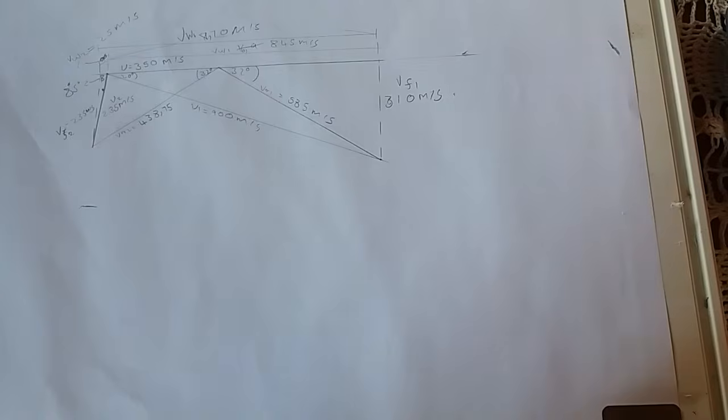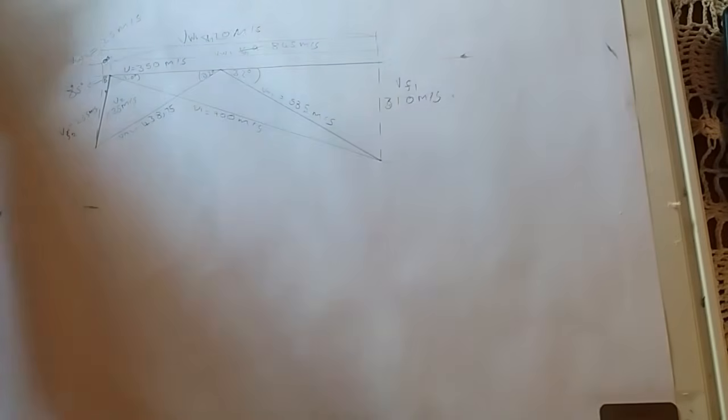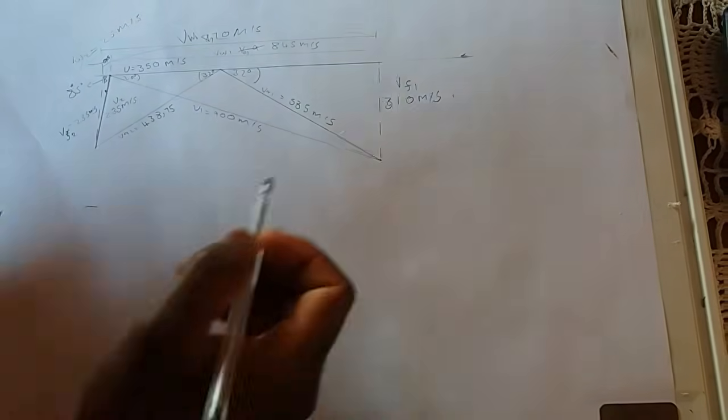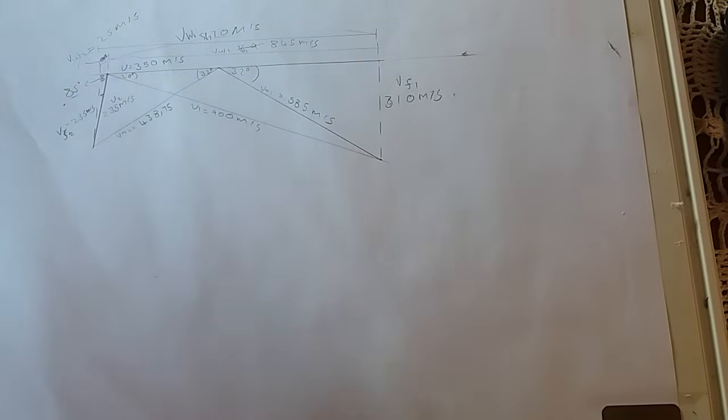5.2. They say use the diagram to determine the angle at which the steam leaves the turbine. The angle at which the steam leaves the turbine, remember, it enters and then it comes out. This is it. It's 85. And then next question, the inlet angle of the blade. We know that it's in from that side, and then it's going out. This is the angle of the blade that they are looking for. It's 32.